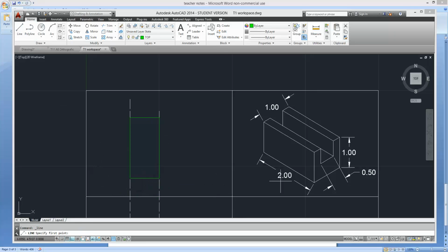The next thing I want to do is draw these views right here on the top view. So I'm going to need to come out 0.25, 0.5, and now if I had the block in my hand and I was just looking at the top, you would see these two little sleeves right here, and then you would see the middle.